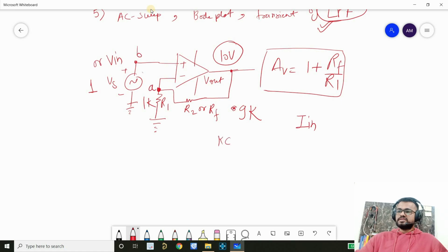So we'll apply KCL on that. For applying KCL, let's suppose the current flowing from here is I in. Let's suppose this one will be I1, this one will be I2, right? And here I in will be equal to I1 plus I2, right? Now, for the people who don't know, we have a very high impedance on this one.